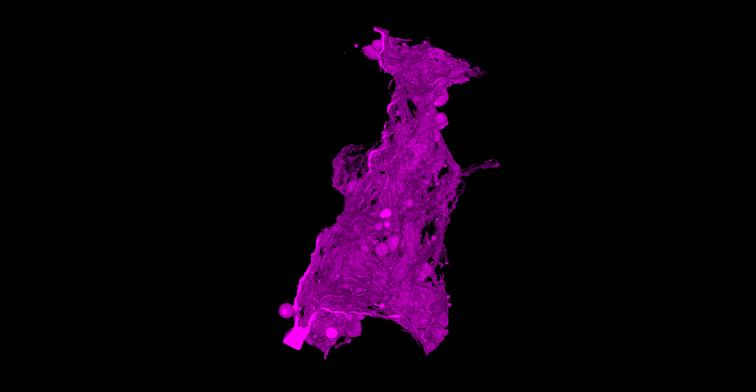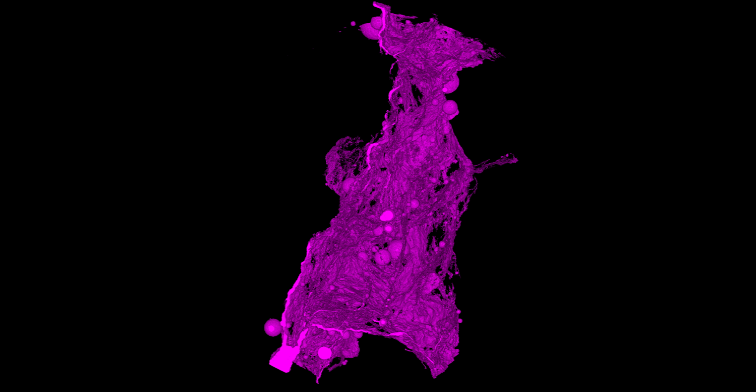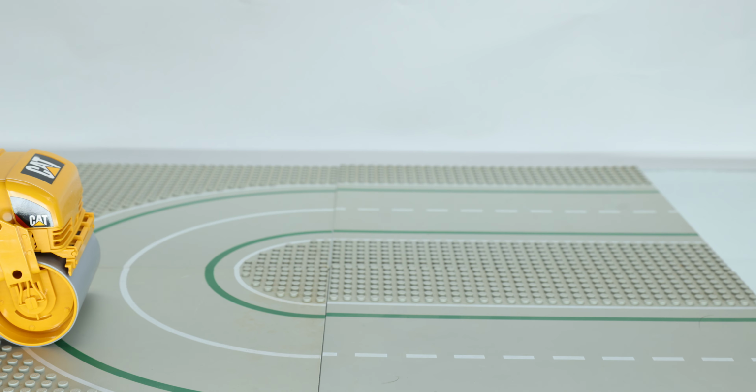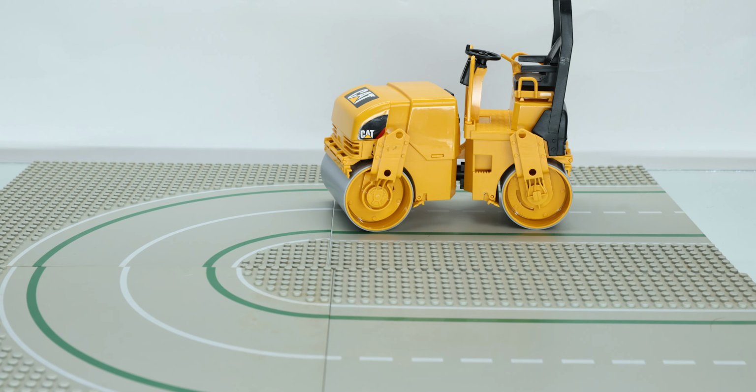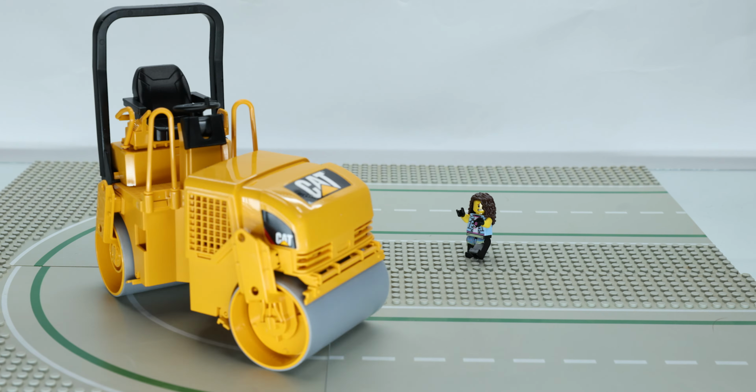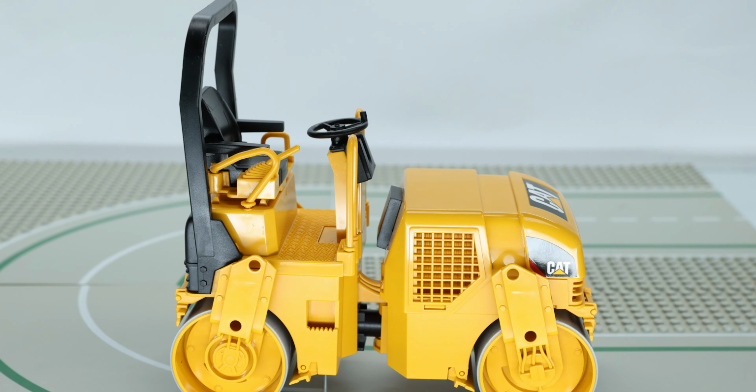Another example is asphalt concrete, which is used on the surface of roadways. The most important aspect of asphalt concrete is achieving the correct density. This is achieved using rollers immediately after placing the asphalt so the microstructure becomes denser.